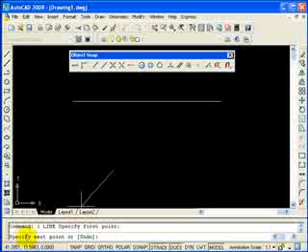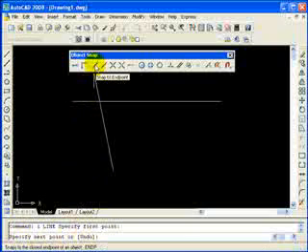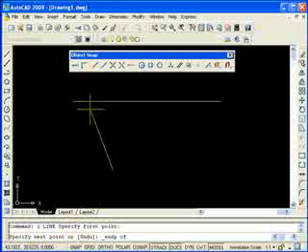So here's AutoCAD asking me for a point, or my next point. Instead of just picking here, I'm going to go over here and click on my snap to endpoint object snap, and as I get close to the endpoint of this line, you'll see this little square come up. Well, that's indicating that I'm getting ready to snap to an endpoint. As long as I see that endpoint square come up, I know that I can click and it's going to hit exactly that endpoint that it's indicating.